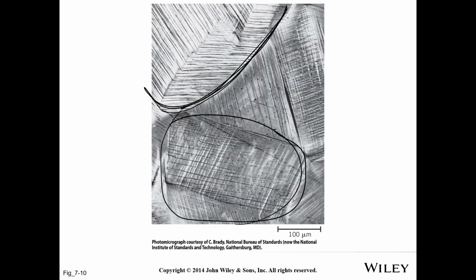But you can actually see in there evidence of how the slip planes are oriented differently in different grains, and you can also see that several slip systems operate on these different grains. You can see some slip lines this direction here as well as this direction. So remember, we've got multiple possibilities for slip. There's more than one set of planes and directions normally.